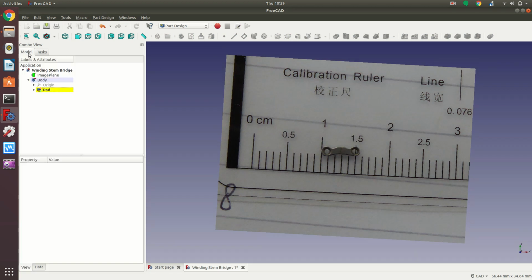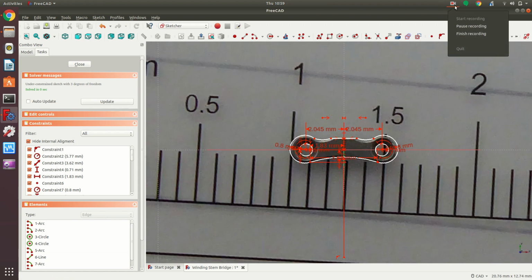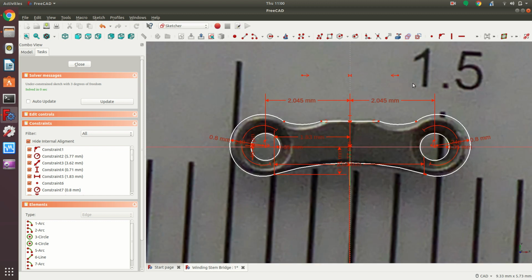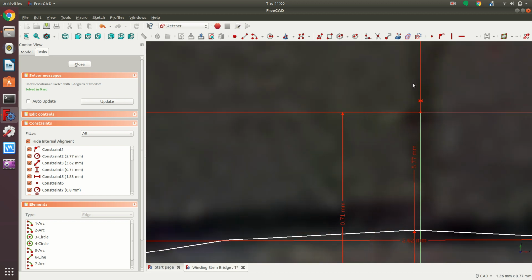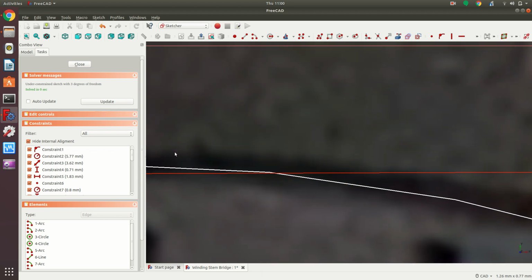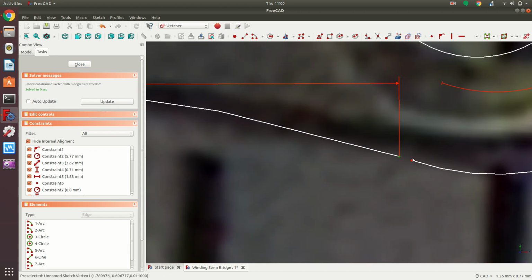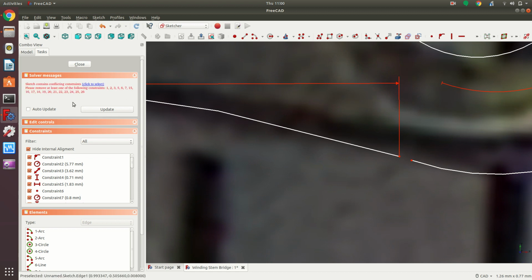That means somewhere in our sketch, okay, so we have a problem. We don't have an object that has just one outside border. We have somewhere a gap, and we got to find it. What we do is we zoom in like total madman, and we follow the outside line. So we go over here, and there it is. See, we've already found it. So what we got to do now is join these blighters. We just put a constraint in here, and now we have an obsolete constraint.